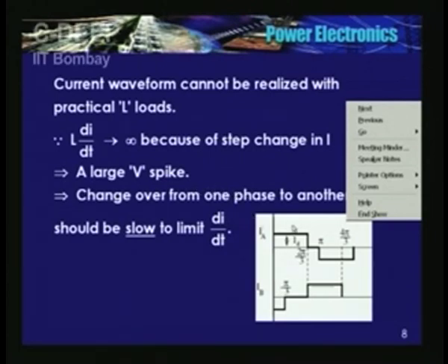What happened in the voltage source inverter? In fact, we had used very fast devices. Very fast devices. We wanted an almost instantaneous changeover from one device to another device. The load may be inductive. Why here do we need a gradual fall and gradual rise? The reason is very simple. The freewheeling diodes take care of this inductive energy. There are no freewheeling diodes here. So these are the differences.